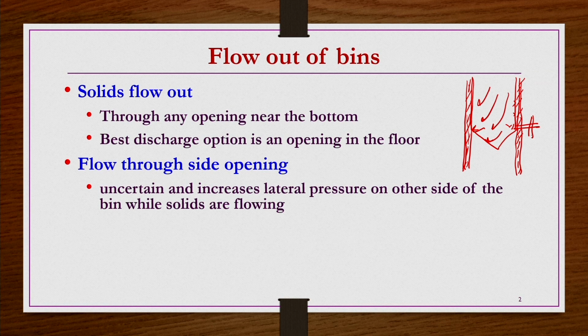So, on the other side of the bin, definitely it is going to have more pressure. So, that is not going to be useful anyway. That is the reason, though it is possible to have openings in the sides, it is not preferable because of these two reasons. One is that you will not be certain about the flow rates, and another is that the lateral pressure may be increasing on the other side of the bin while the material is flowing out.